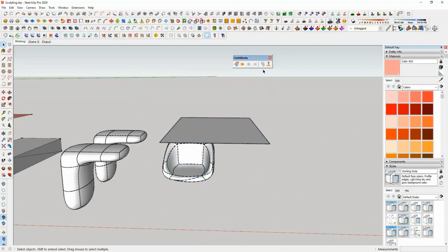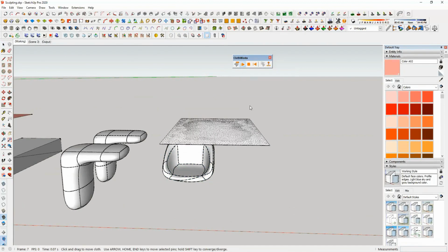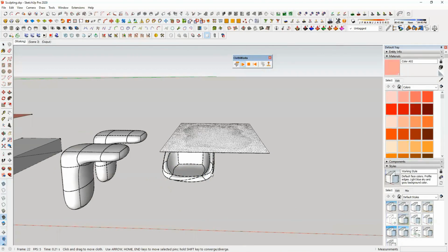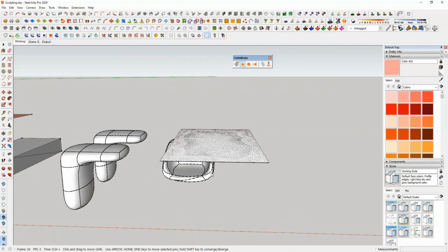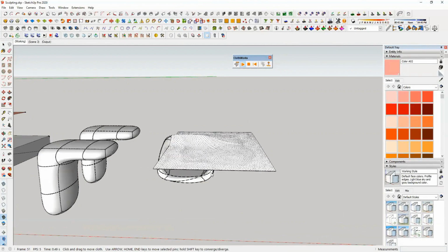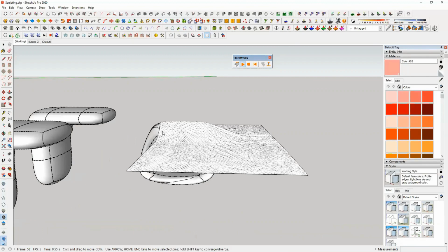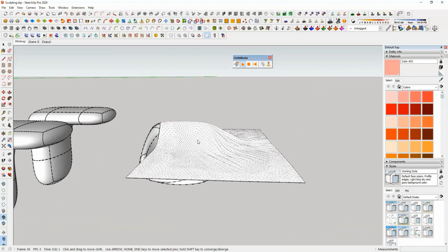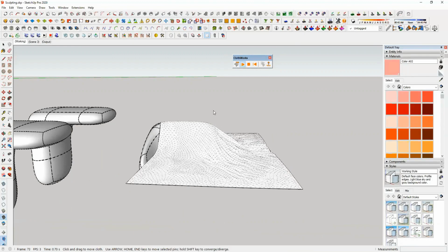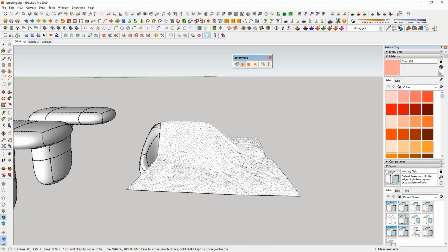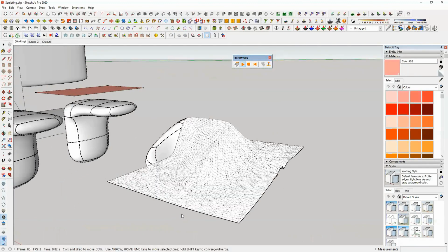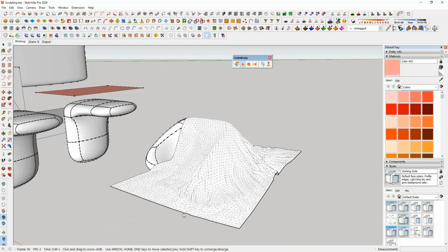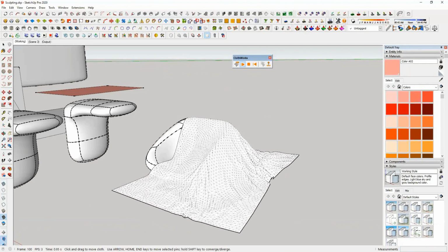And if I just click on play from the ClothWorks toolbar, you will see that it will start falling down as if it is falling down due to gravity. And at the point where it intersects the collider, it will start wrapping around the object as if it were a real cloth. So this is the real life simulation of a cloth.